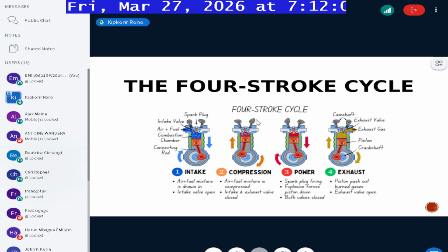What normally happens is that the CO2 will simply stay and occupy part of the volume. It's part of the reactants, but it cannot react to produce anything. So the fact that some of the volume of air and intake gases is taken up by gases that cannot react is what normally causes loss in both volumetric efficiency and thermal efficiency of the engine.